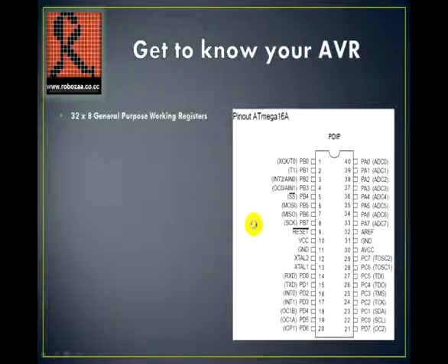There are 32 general purpose 8-bit working registers. This microcontroller can work at a maximum of 16 MIPS through a 16 MHz external clock crystal.